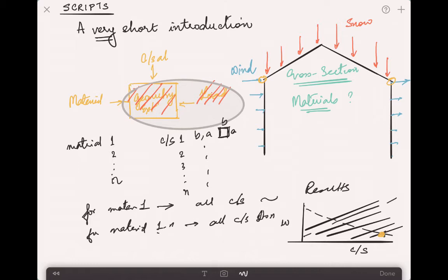And the other advantage of using this script is that any model that you make which is graphical is quite large. And if you write it in form of a script, then it's just text, and you can save it as a text file, and you can share it with anyone you want. And if you comment it properly, people know exactly what you're talking about in your code, and they can run it on any software or any Abaqus version or any Patran, whichever script you're making, to run the analysis. So they don't have to open this large database file which consists of all kinds of diagrams and pictures and all that, which is going to take a lot of space. So this is quite an easy way of setting up a problem where you're going to use repeated things.